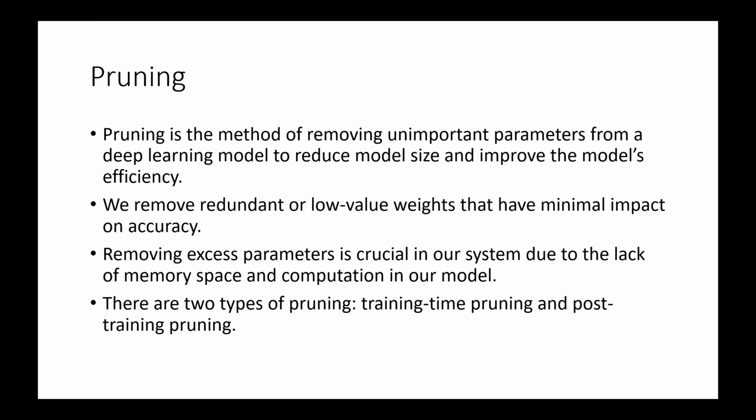So we don't want to load any weights that exceed the 2 kilobytes, and we also need enough space for other operations. So we have to make our memory more concise. We have to reduce the number of weights we need. For this, you have to remove a couple of weights which are not important for the ML process.